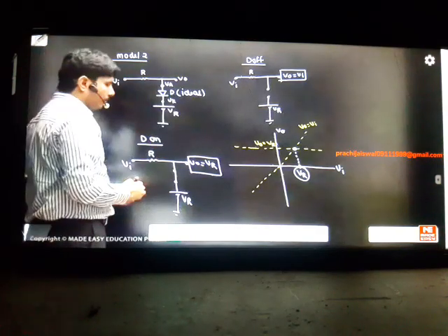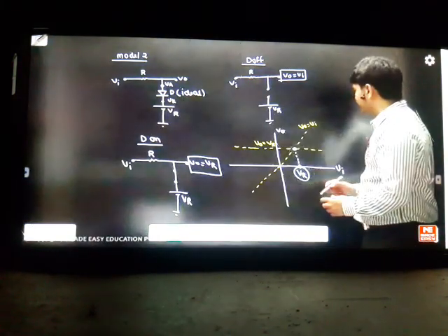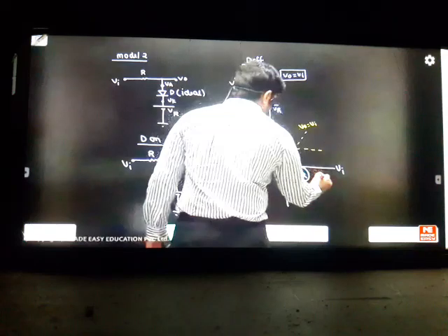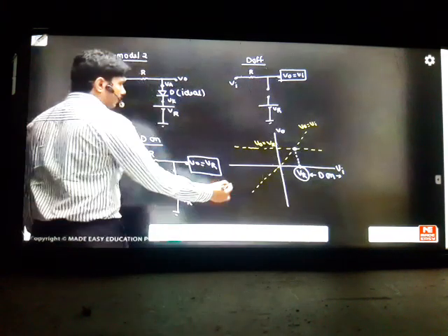So any value you apply to the anode, if it is greater than VR, the diode will turn on. So I'm expecting above VR. Understood that above VR, the diode will be on. Seeing the diode model, we can tell. Okay, below VR, the diode will be off.